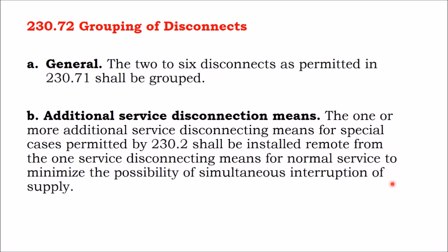So if you want to put an additional disconnecting means onto the system that's power operable, you can. It might not be hand controlled. It might be above and beyond what you need. You still need a hand operated switch out there. That power operated switch would not be counted. Still could be by your local jurisdiction though.